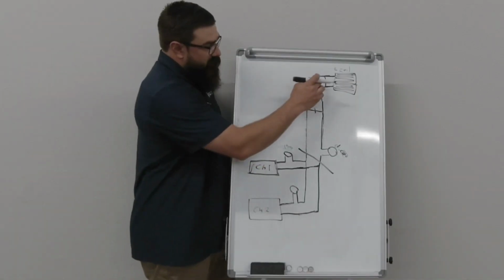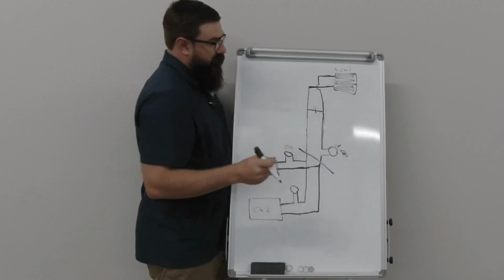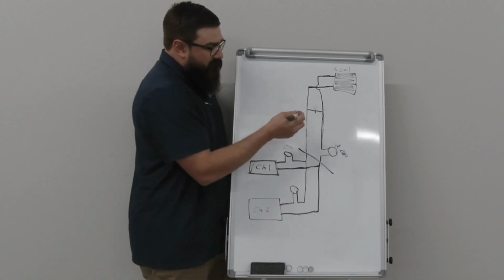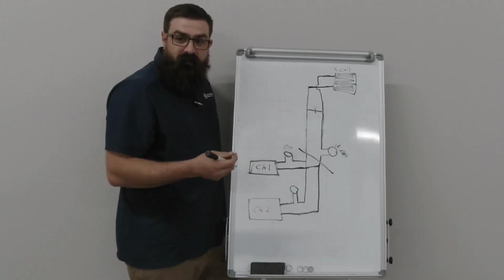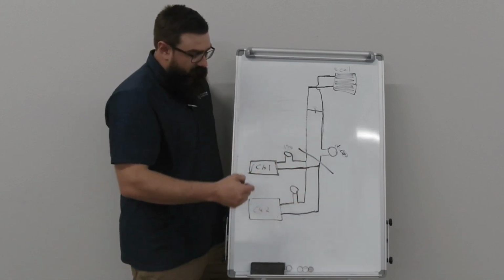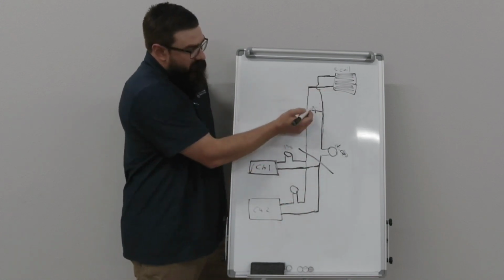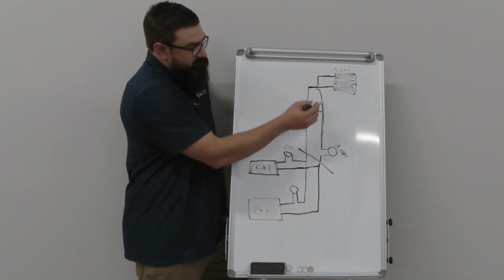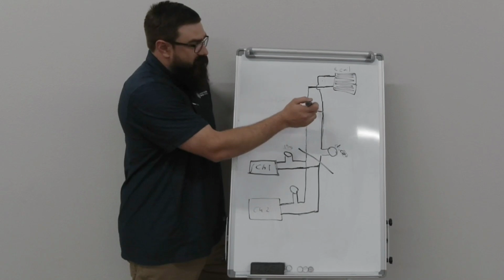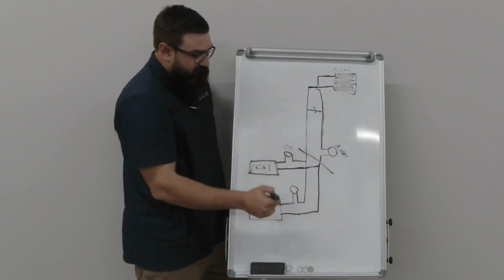That is definitely typical on buildings that don't have a three-way valve on the coil. Some buildings only have two-way valves, and then we have to have a bypass because you have to be able to maintain your flow through the chill water system. So as these open and close, so as these close, this will open. As these open, this will close. So whatever's not getting pushed through the coils goes through this bypass to circulate the system to keep your flow equal.